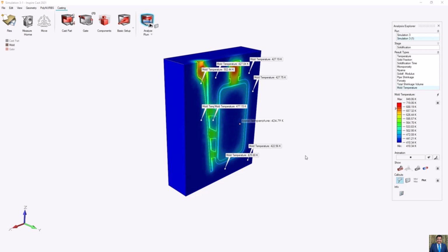And I can also tell you one tip when you cast. When you fill with aluminium, we have a filling speed of 0.6 meter per second, and when you reach that level, you need to change the speed from 0.6 meter per second to 0.3 meter per second.